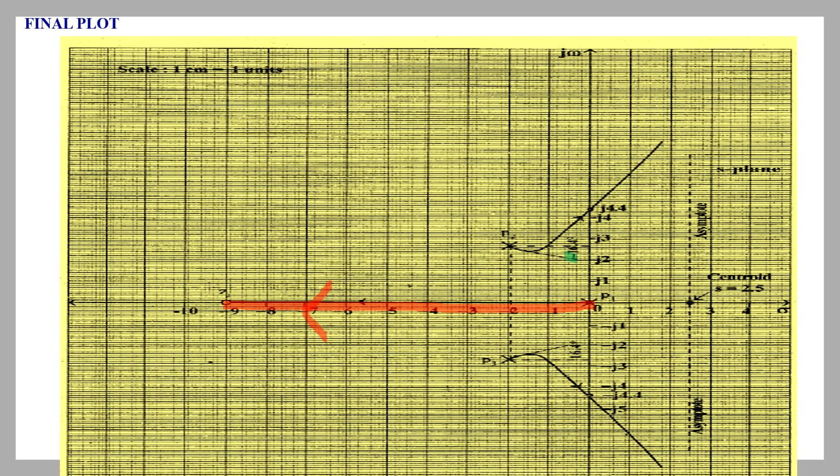So the branch will start at P2, take the angle -16.4, then it will meet the j4.4 at the gain value K equal to 8.8. Then when K is increased further, the branch will move to the right of the S plane. It will travel, then take plus 90 degrees, that is, it follows the asymptote shape, and it will go to infinity in search of zeros. So this is branch number 2, right?